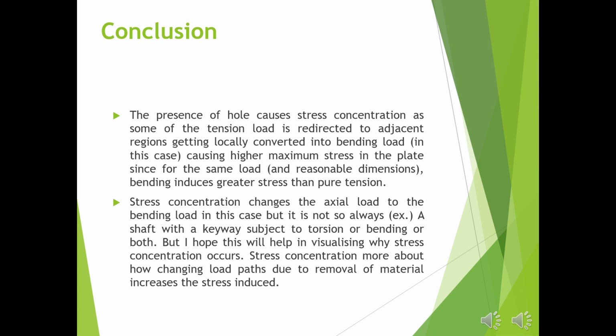So in the case study that was shown previously, we saw that the stress concentration is caused by the presence of the hole, because the presence of the hole causes the tensile load to get locally converted into a bending load. In the example that I have presented, the stress concentration problem is caused by conversion of the tension into a bending problem locally. However, that is not always the case for all stress concentration problems.